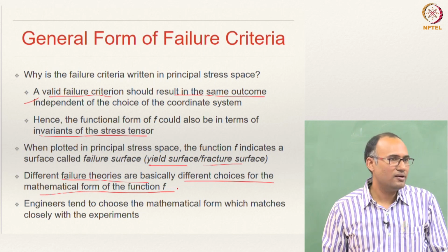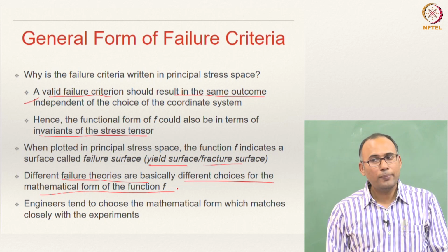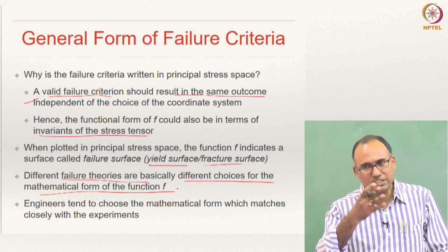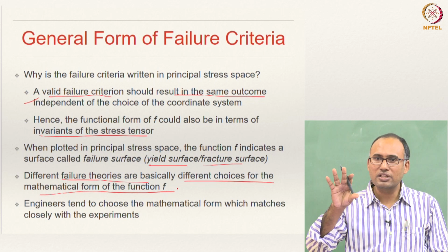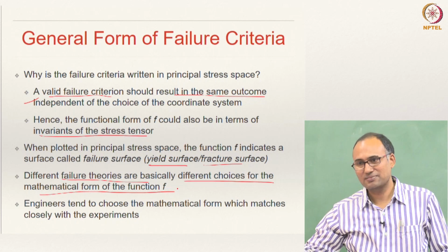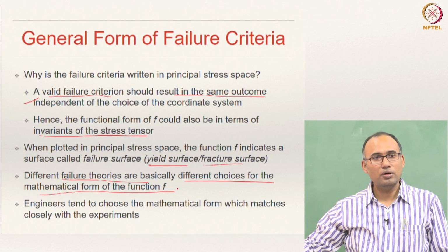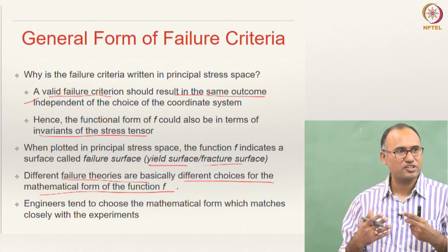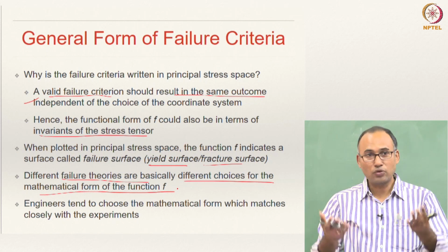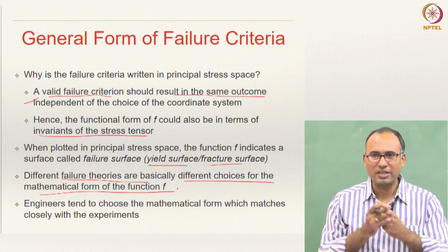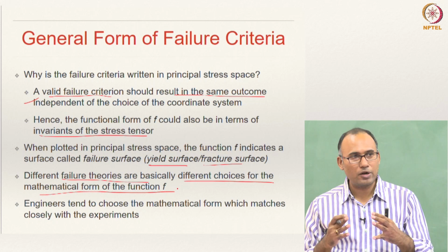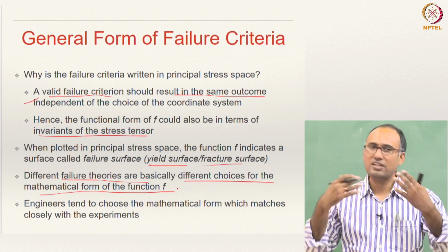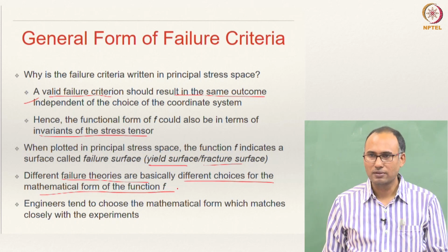And please understand that just because a particular failure theory is representing experiments perfectly well for a given material, does not mean that that failure theory is going to be good for several other materials. So, this failure theory is only a mathematical abstraction or mathematical representation that we are seeking in order to represent the behavior. But your failure theory that you have prescribed might actually break down for some other cases. This is something that we should keep in mind.